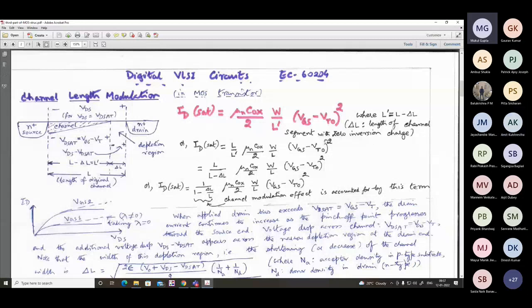And similarly, that was an n-type polysilicon gate. Suppose you have a p-type polysilicon gate, and the acceptor concentration is 10 to the power 20. Then, for simplicity, we'll assume that the Fermi level is almost coincident with EV. So for a degenerate p-type semiconductor, the Fermi level is coincident with EV, the top of the valence band, whereas for a degenerate n-type semiconductor, the bottom of the conduction band will be almost coincident with EF. So EC and EF will be coincident for degenerate n-type, whereas for degenerate p-type, EV and EF will be taken to be coincident.